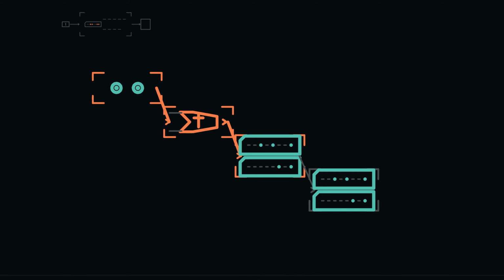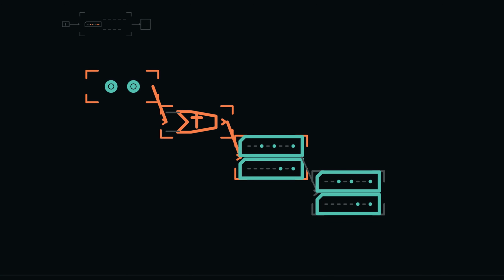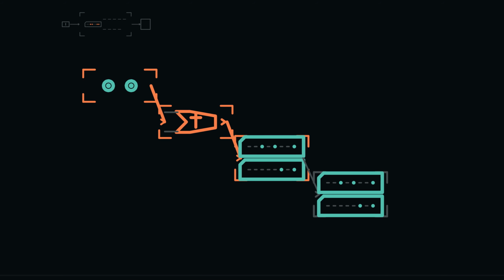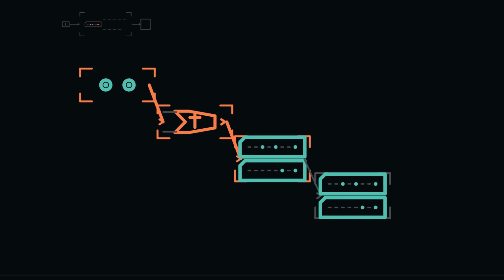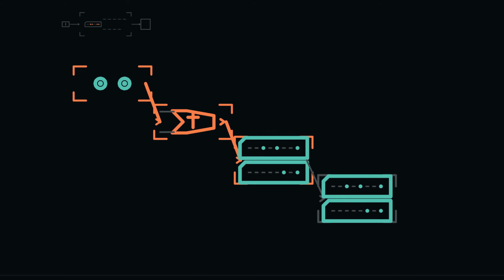Try the reverse direction. The bytes 29 and 05 are stored at the program counter. Using the SE8 field layout, identify the opcode, the selected register, and the operand mode. The result is add immediate to R0 with 5 as the immediate value.